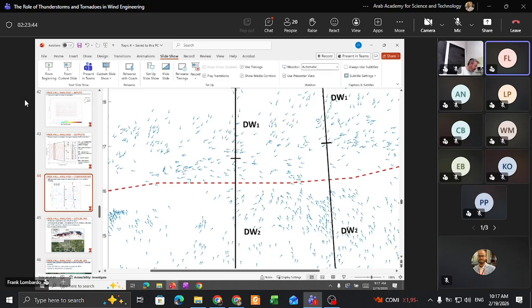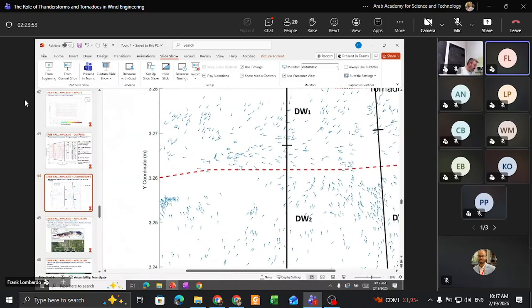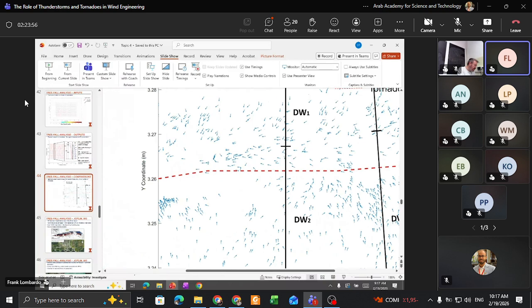You can see that on this side, and the tornado is actually changing characteristics here, the trees in general are falling inward towards the center. The tornado is moving in this direction. You can see some of it out here like this, some fall pattern. Once you get over here, it starts to fall more like this towards the tornado. Here, things are closer to the direction of translation. And up here, it's something like this, right? So you can see this clear convergent pattern in the tree fall.